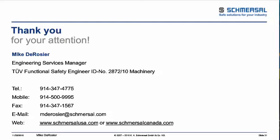That's the minimum. Regardless of what you come up with, that's the minimum performance level. This function needs to meet performance level D. Even if your risk analysis says C, they want it to be D. And they're referring to performance levels, which is straight out of ISO 13849. And you'll see in the references in the back of the standard, ISO 13849-1 and 13849-2 are typically referenced in any new or updated standard. So the ISO standards are becoming more globally harmonized and being implemented into national standards now.